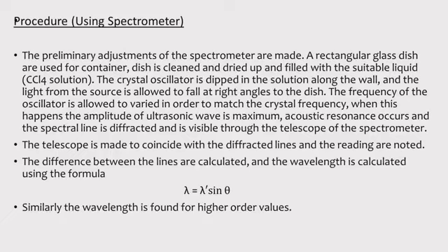This piezoelectric crystal is placed inside the dish in such a way that it is parallel to the edges of the dish, and it is connected to an RF input which varies the frequency range. After we place this crystal inside the dish, we vary the frequency of the oscillator in such a way that the crystal's natural frequency is matched with the frequency of the RF input. And when this happens, resonance happens.